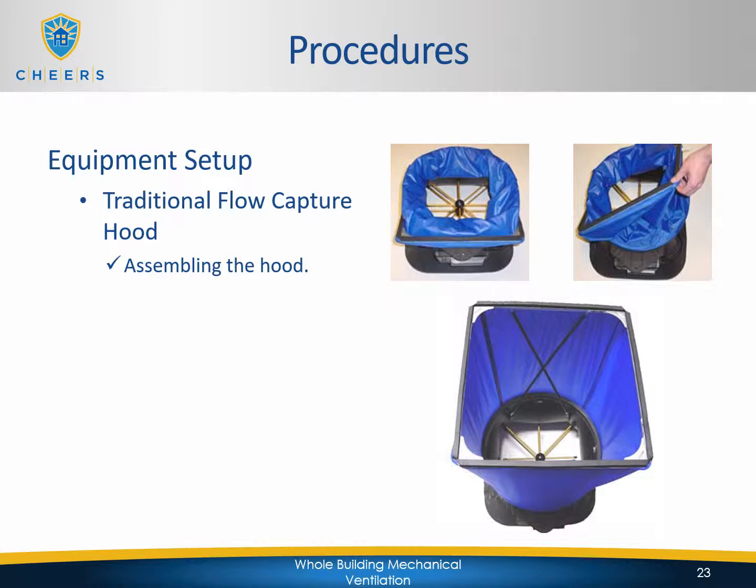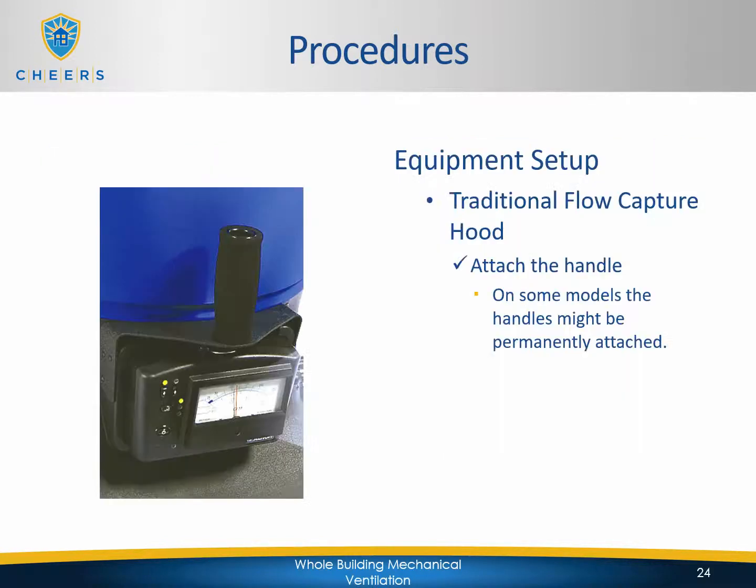For the traditional flow capture hood, you're going to assemble the flow hood as instructed by your manufacturer's instructions. You want to attach the handle to the flow hood. On some models, the handles might be permanently attached, so it just depends on the model of the equipment that you're using.